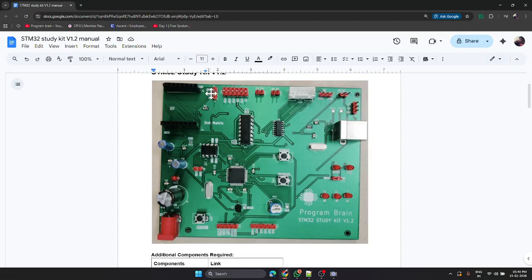That's why I gave pins here: for SPI here, I2C here, and UART here. We can directly connect the logic analyzer pins to these pins and see what input and output data are coming and going. That's why I gave the pins here.